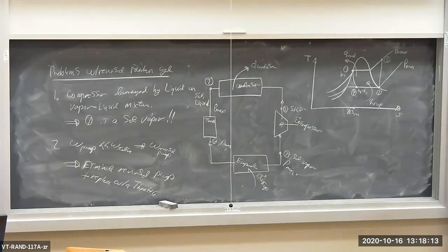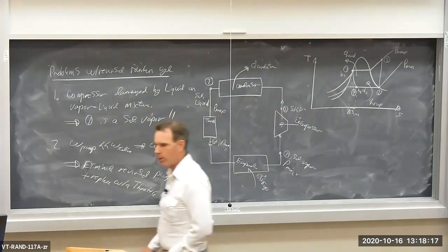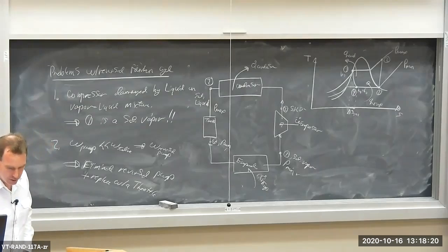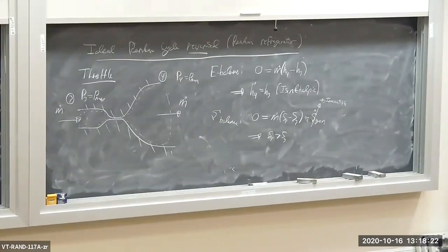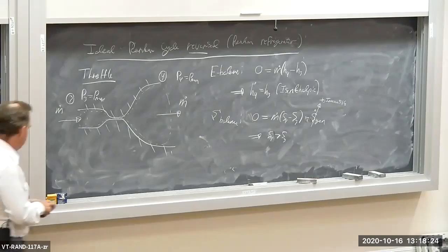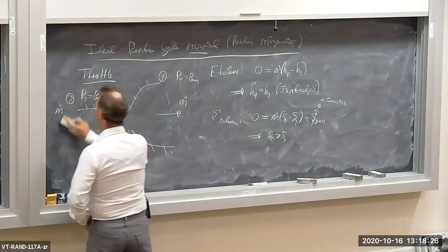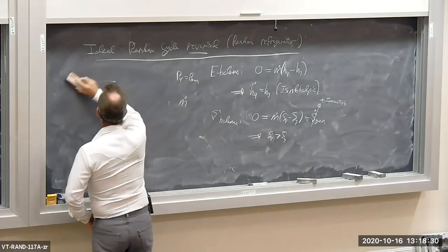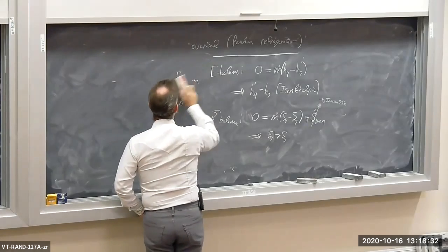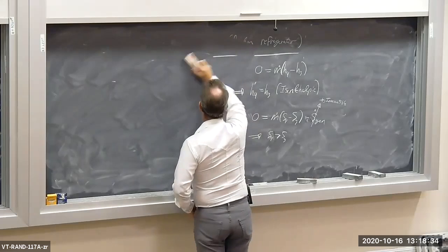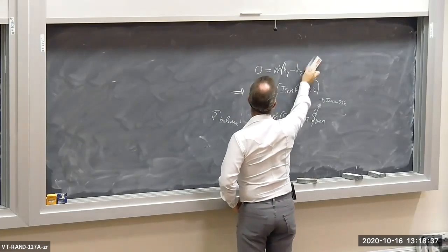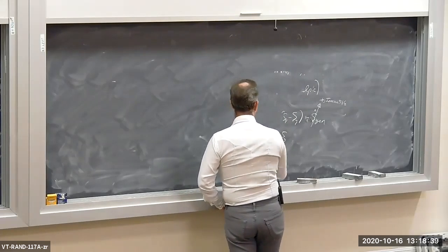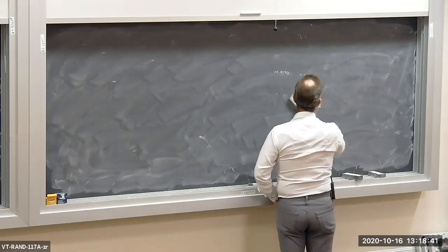Now there are all sorts of deviations away from the ideal cycle. So there are all sorts of things that can happen to make this thing non-ideal. Let's just go over some possible variations on the refrigeration cycle from the ideal cycle. Of course, the obvious one is having isentropic efficiency for the compressor being different than 1. So having irreversibilities in the compressor.